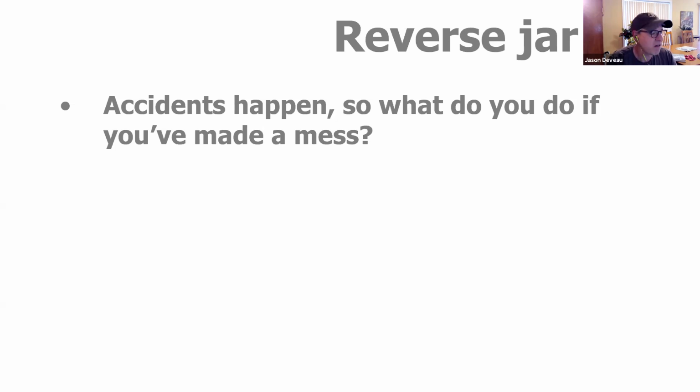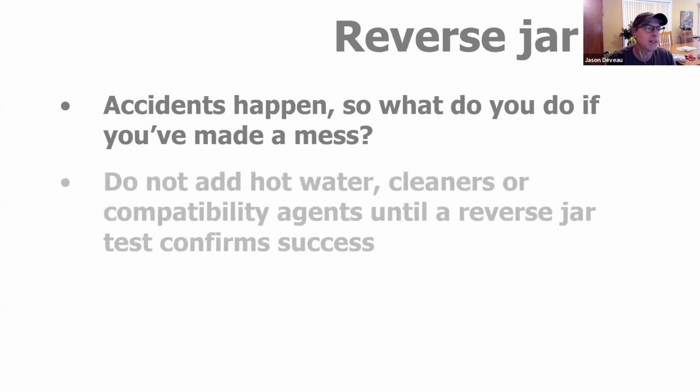So if you do make a mess, what do you do? Everybody's instinct: fill it with hot water and detergent and try to break it up, pump it through. Please don't do that. That's not your first go-to move. Your first go-to move should be to perform what I'm calling, or what Mike and I call, a reverse jar test. Scoop some of it out.